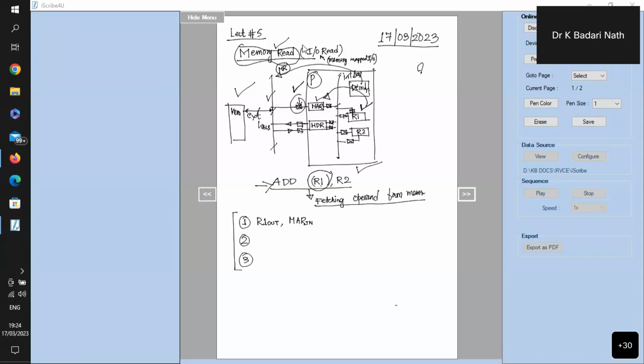So now I am giving one signal called a read signal to the memory. Whenever the read signal is generated by the decoding circuit, the bus interface circuit will generate MR. So now I am informing the memory that I want to read from it. Which address? The address which is already placed in the address bus. So the read is initiated, and the address is there in the bus. Now you provide me the data. But the data will not be provided immediately. I have to wait for that. How much do I have to wait?